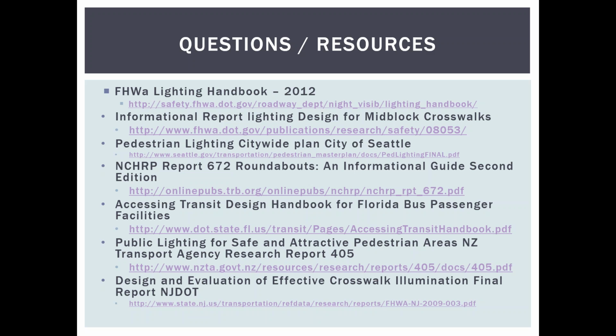No, in fact, I don't think that the LEDs are problematic in cold areas. The only thing I've seen were the LED street lights, sorry, traffic signals. The red, yellow, green traffic signals have sometimes been problematic because the LEDs themselves generate very little to no heat at all, and there have been issues that way. But as far as when you have an overhead light source and the light is down at the bottom, I don't see any issues with snow accumulating on it or something that's going to block it at all. They actually thrive in cooler temperatures, and they don't do as well in hotter temperatures.